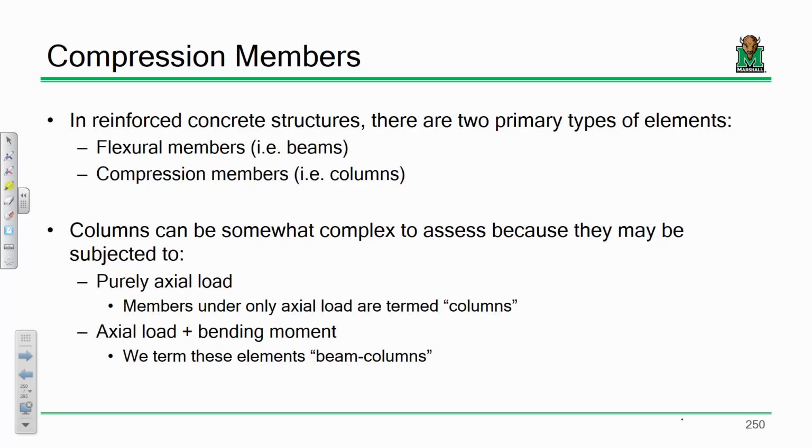So, the best case scenario for a beam is that phi equals 0.9. But for a column, phi is pretty much going to equal 0.65. All right? Now, there are cases, and this is going to become clear in a second, where phi can be 0.75, and you'll see the difference and understand why. But by and large, phi values are demonstrably lower in columns than they are in beams. As a result, that's basically saying we're cutting the amount of usable capacity that we can use.